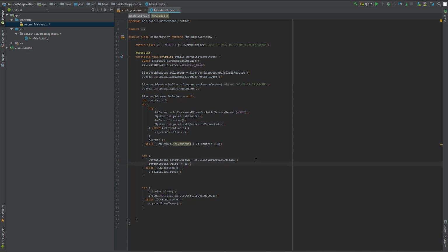Okay, so now we've sent a byte of value 48 decimal to the serial port, and when our Arduino receives this value, it's going to send the whole alphabet back out to the serial port, and we're gonna want to receive that alphabet and all those characters, all those ASCII bytes, and print them out to the console window to confirm that indeed we have received all that data.